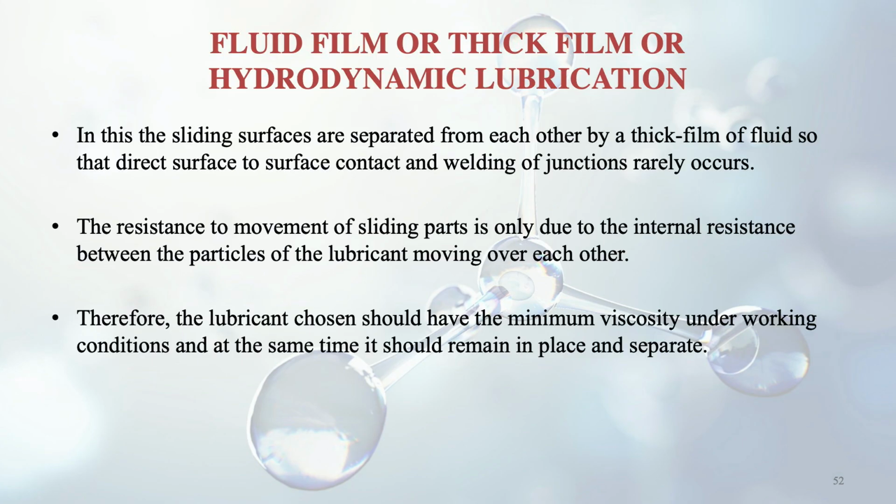And for the lubricant chosen, that's why you should have the minimum viscosity, because if it is too viscous, then also the movement will be hindered under working conditions. And at the same time it should remain in place and separate. So two properties are needed: it has to not be very highly viscous, and it should also not be very light or very less viscous, such that the fluid flows away. So that should also not be the condition.